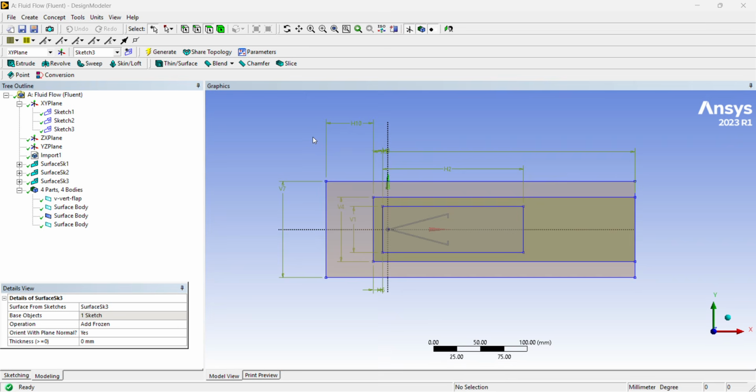But when you go to the meshing, you will realize that the meshing in the three zones will intersect, because these surfaces are overlapping. So now what we have to do is change the overlapping. We have to create three separate, independent zones. So I will remove one surface, Boolean out one surface from the outer one. So let's start with the outermost one.